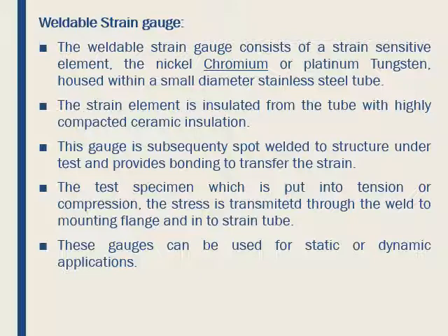The semiconductor bonded strain gauge is a wafer with the resistive element diffused into a substrate of silicon. No backing is provided for the wafer elements, and the surface to be strained needs extra care since only a thin layer of epoxy is attached to it.